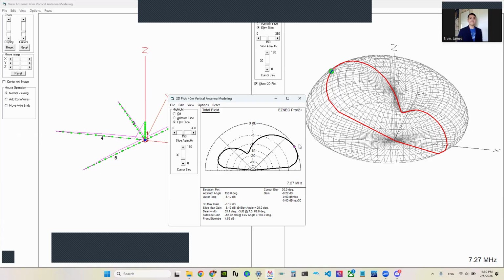So let's say there's 100 ohms of impedance in the system. 90 of those ohms are radiation resistance, and 10 of those are ohmic resistance. Well, that's nice, 90% efficiency for our system. But say that we have 10 ohms of radiation resistance in our system, and then 5 ohms of ohmic resistance. That is two-thirds of your power being transmitted, but that is an additional third of your power being given off as heat.